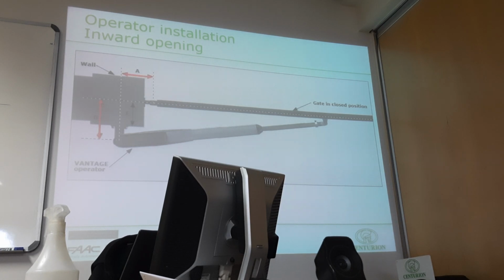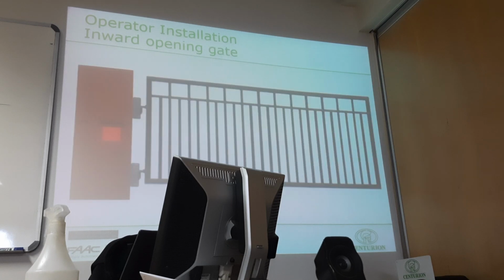There's our A, there's our B, and our E. You understand what your E is? It's your pillar depth, from the center to the corner. That will determine what your A and B can be on a specific 400 or 500 motor, depending on the motor and the angle you want this gate to be able to open. Okay, so your E value runs horizontal.